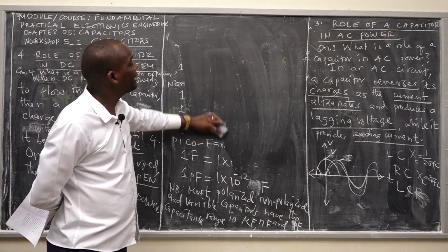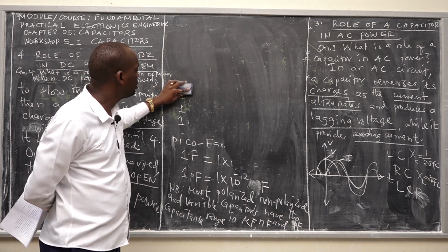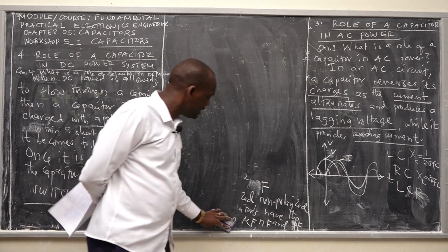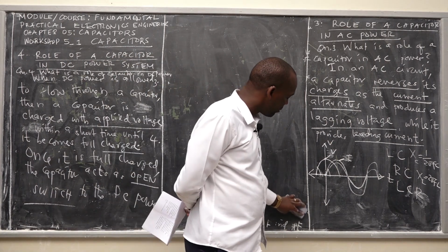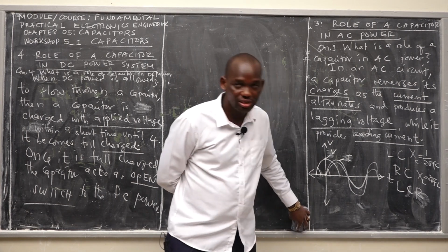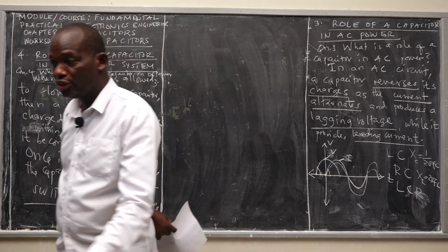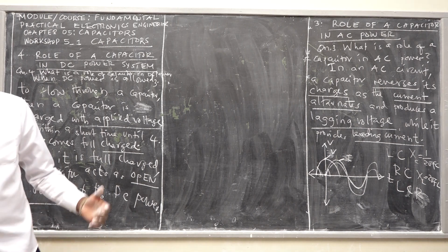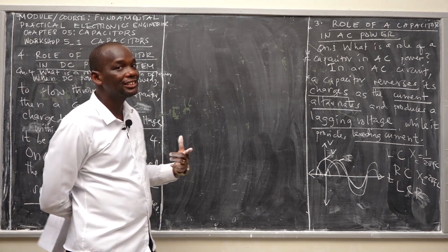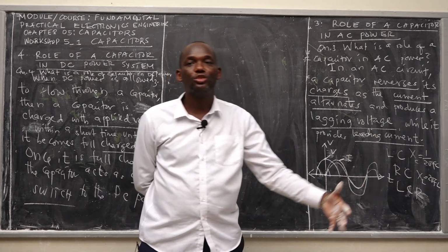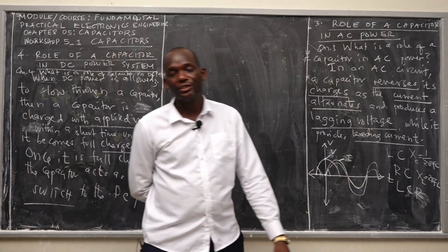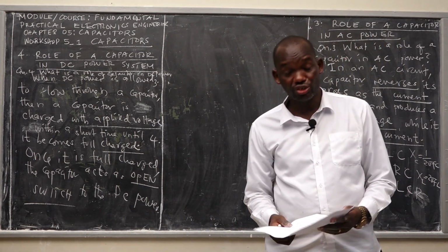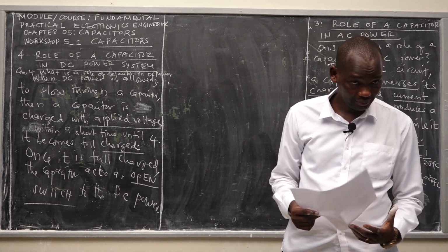Right? By that time, the capacitor stopped what? To charge. So when it is fully charged, by that moment you say that the capacitor is full, fully charged according to the applied what? Voltage. So when the capacitor is fully charged, then the capacitor acts as an open what? Open switch. That's why we say that the capacitor does not allow the DC voltage to pass through it.